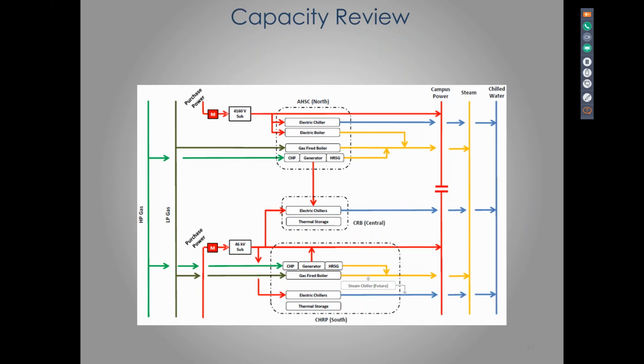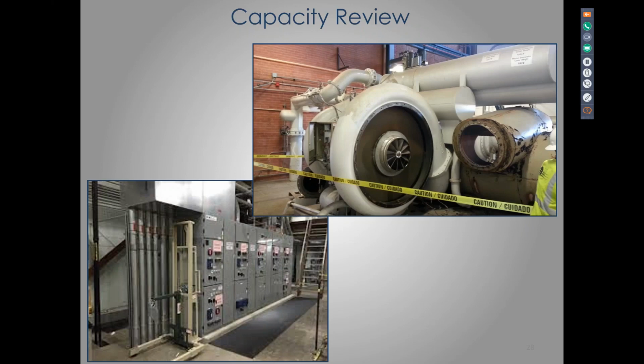All right, so I'm going to talk a little about the distribution system. Here's another kind of graphic of how the energy works here, the energy flows here. If you haven't figured out by now, I'm a mechanical engineer, and this is my kind of thing here, flow diagram. So when we're in the plants, we're looking at equipment. What you see up there on the upper right-hand side is a great big side-wheeler Crane R11 machine. The refrigerant's obsolete, out of date. The machine itself, efficiency is nowhere near what current technology is. This one aged out and now gets replaced with something way more efficient with a refrigerant that doesn't have any global warming potential.